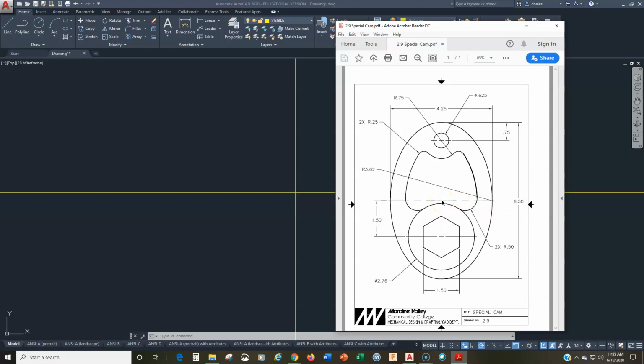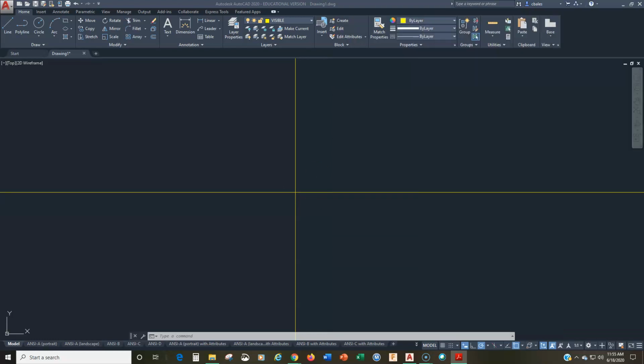So how can I do that? Well, I could actually do either one, to be honest with you. Since I've already identified the center, I'm going to use the center option. So I'll choose center. But I have to be careful, because this first distance that I'm going to do, whether I do the vertical or the horizontal distance, has got to be half of the length that's given in the drawing.